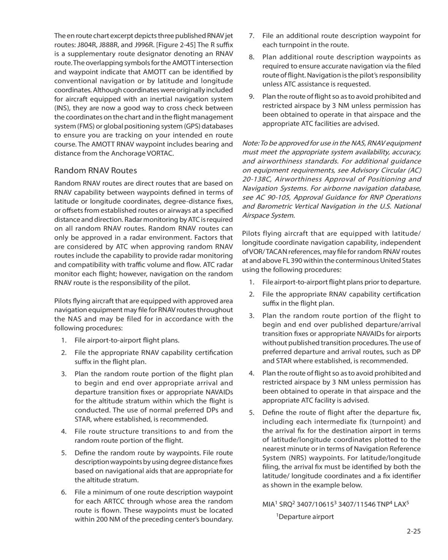5. Define the route of flight after the departure fix, including each intermediate fix, turn point, and the arrival fix for the destination airport in terms of latitude/longitude coordinates plotted to the nearest minute or in terms of Navigation Reference System, NRS, waypoints. For latitude/longitude filing, the arrival fix must be identified by both the latitude/longitude coordinates and a fix identifier as shown in the example below.